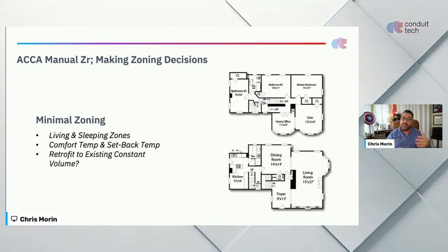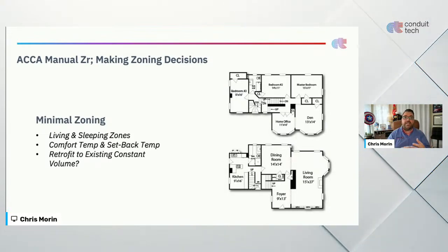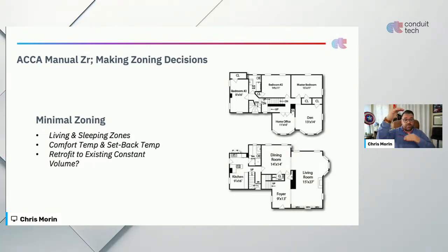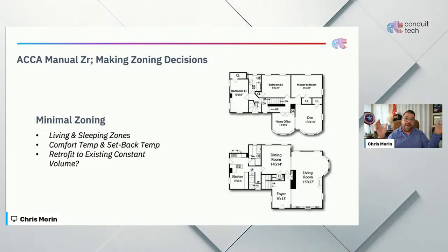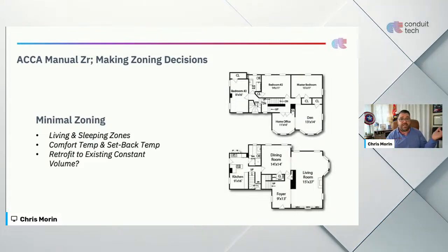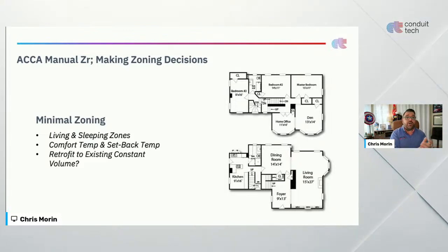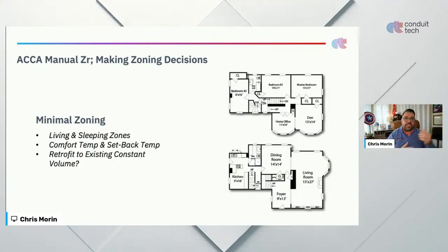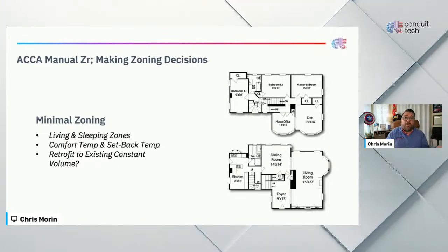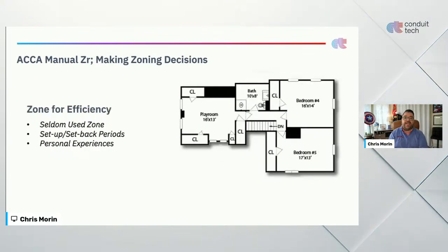But you tend to burn a lot more electricity or a lot more gas, and you're going to run across these comfort problems because a lot of times you have just one large trunk or 2 large trunks that you're actually going to zone off, and you have incompatible rooms, like we talked about at the beginning of the presentation, off of that same trunk. And we tend to overheat or overcool some of those rooms in order to provide the higher level of comfort for floors, let's say. Ideally, we're zoning with equipment in that instance. All right, I'll stop beating that horse.